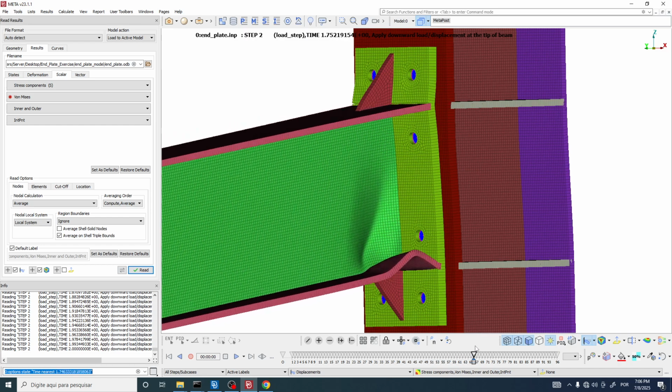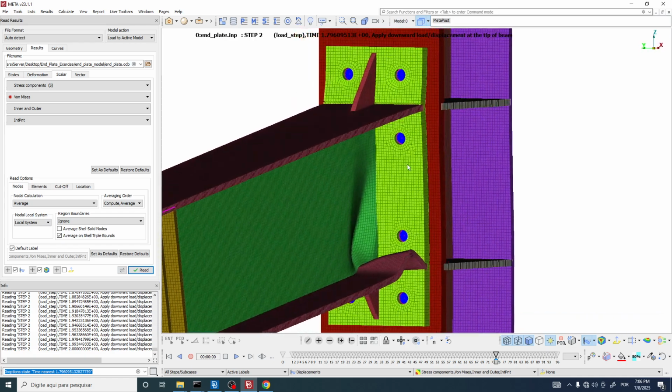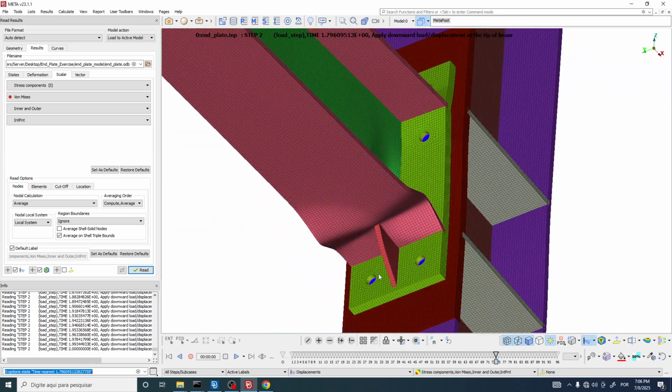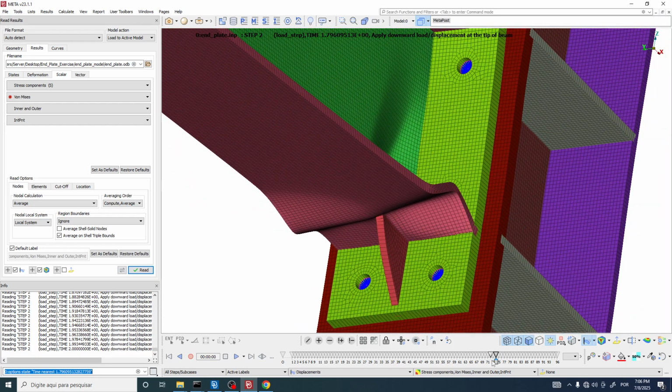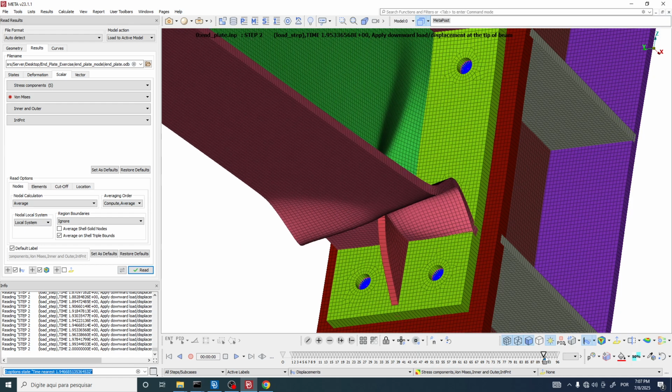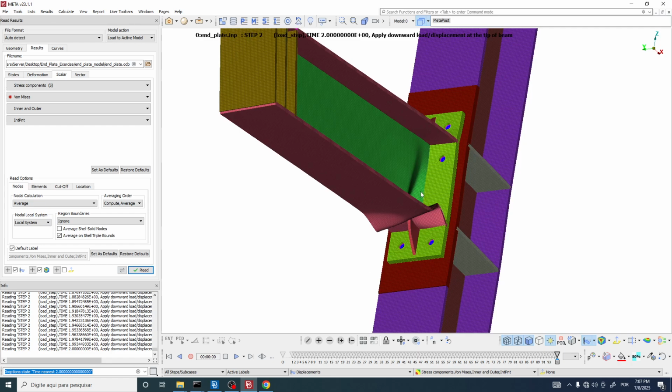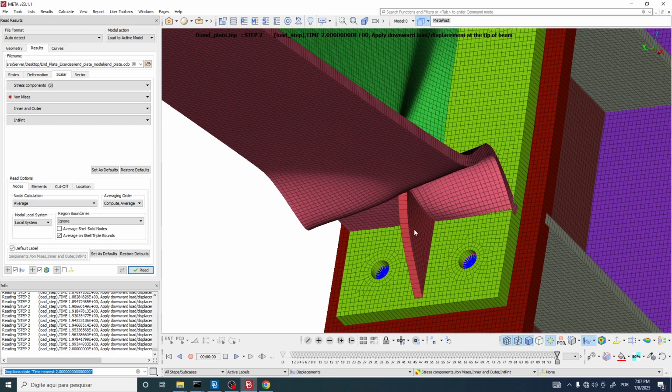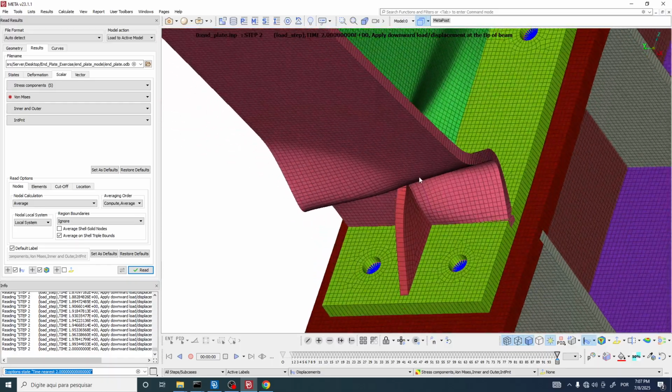You see? It's deforming a lot because the displacement that we applied is very large. We actually have a lot of buckling occurring here, which is something that is expected. You're going to see in the images of the experimental data that this actually happens in the physical model, which is so nice, you see. It's really nice to create a simulation and compare with experimental data, and also compare to the pictures of the experimental data and see that what we have calculated here actually represents the reality. I don't know, guys. For me, this is really nice.